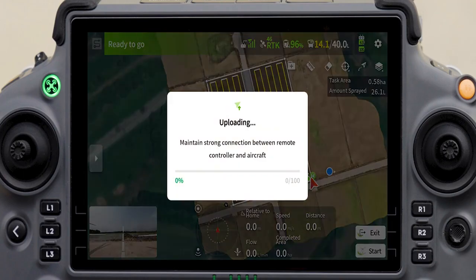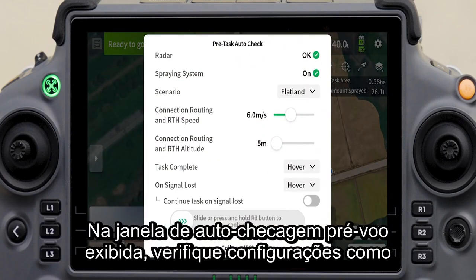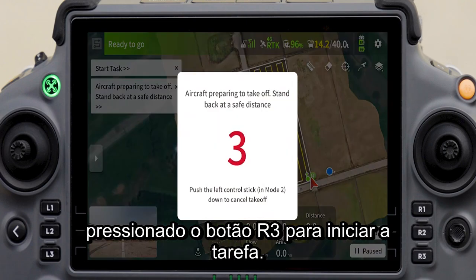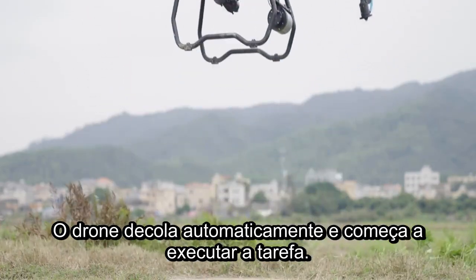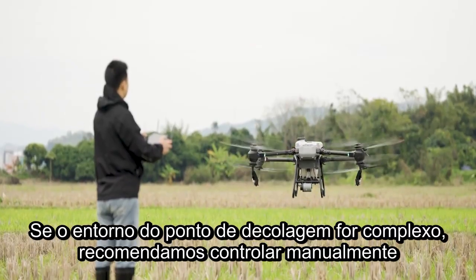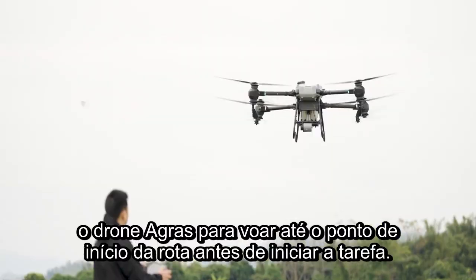Click Start. In the pre-flight auto check window that is displayed, check the settings such as connection routing and RTH speed and connection routing and RTH altitude. If all settings are correct, slide right or press and hold the R3 button to start the task. The drone will automatically take off and start to perform the task. If the surroundings of the takeoff point are complex, we recommend that you manually control the Agras drone to fly to the start point of the flight route before starting the task.